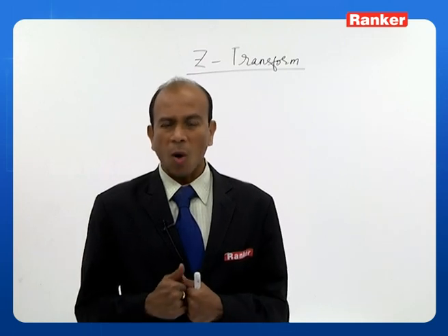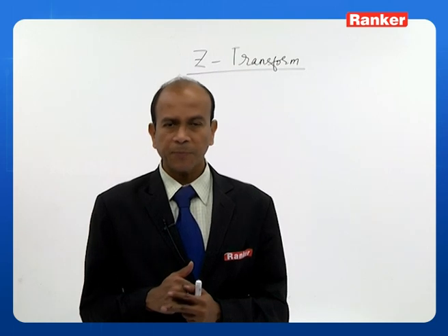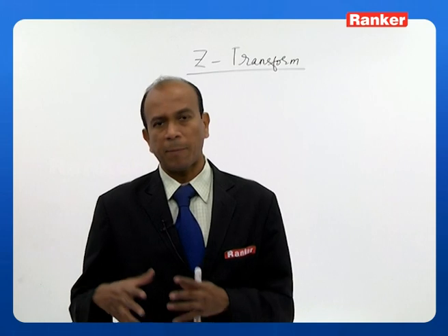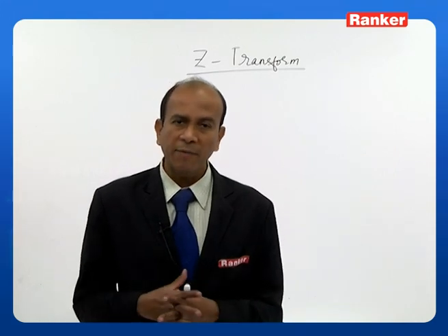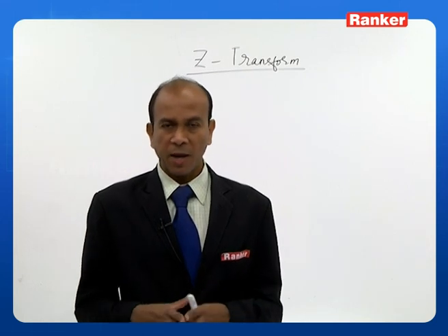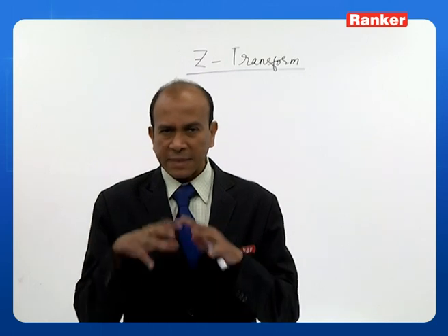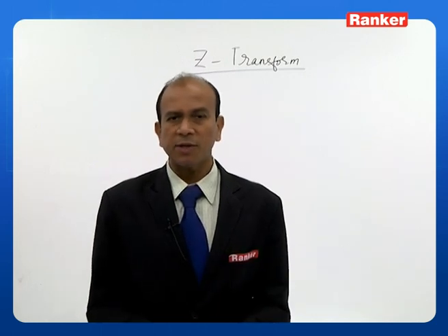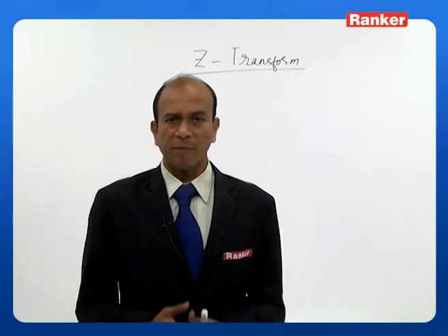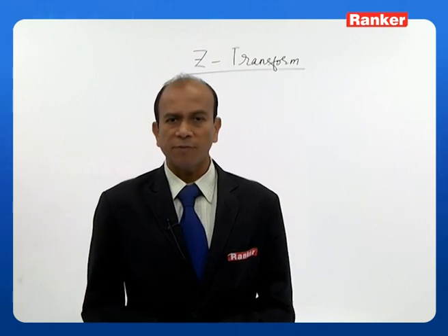This is how we try to calculate the system functions. So if I make x(n) equal to delta(n) and apply it to a system, then X(z) will be equal to 1. H(z) will be equal to Y(z), and if I calculate the poles of the function, and if all the poles lie inside the unit circle, that is mod z equal to 1, then the system is said to be stable. So H(z) is giving a lot of information. We can calculate the stability of a system if I know what H(z) is for such a system.